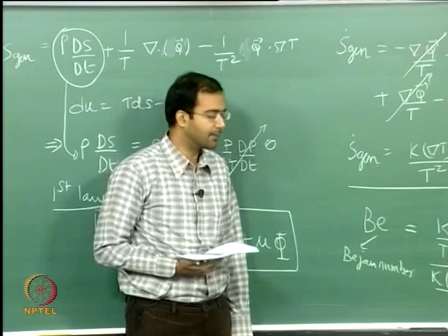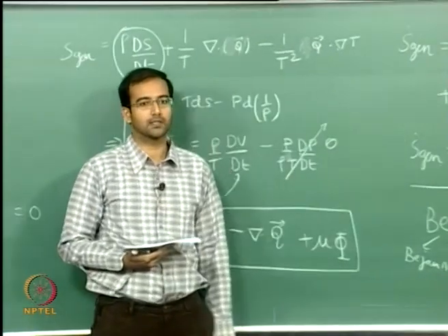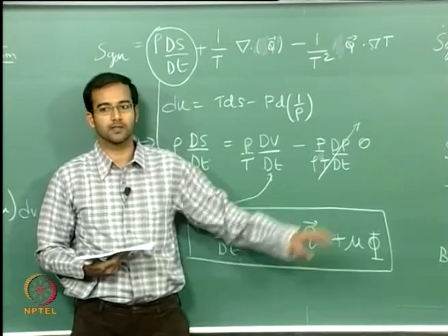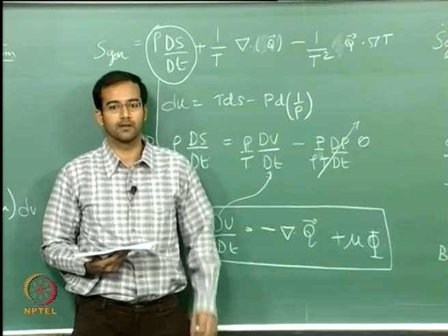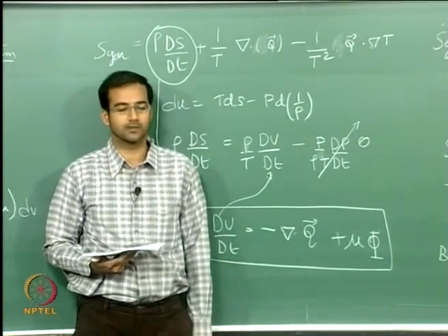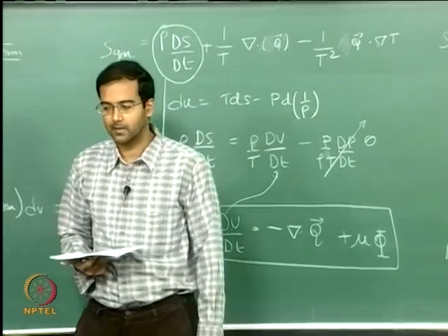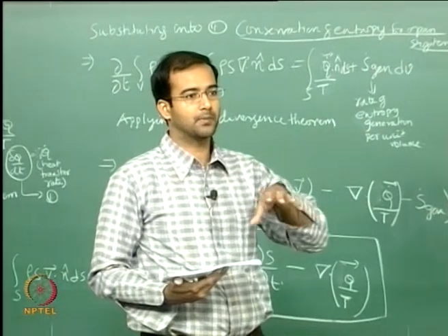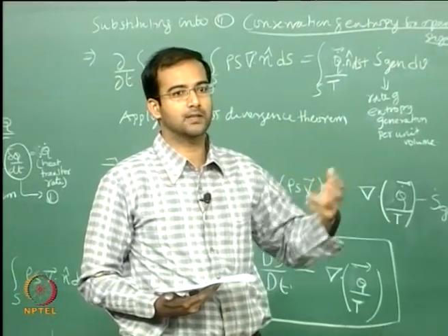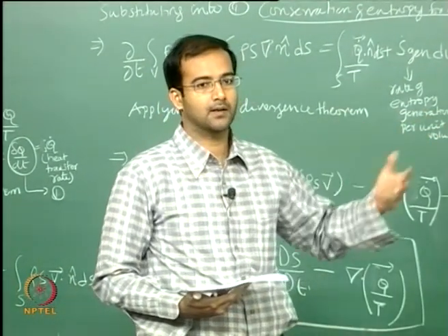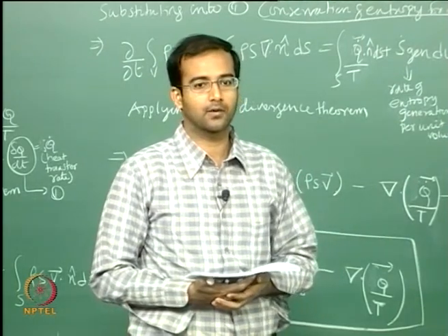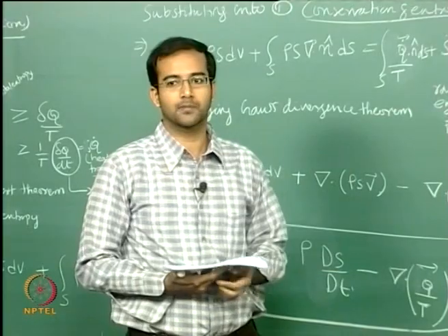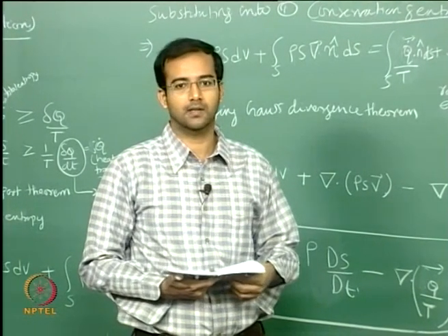So basically this can be plotted just like you plot your isotherms and heat flux lines. You can plot the entropy generation due to each of these and visualize how it looks. It's a very useful tool, and you can see in which location in a particular system your entropy generation is by the conduction part and where it is by viscous dissipation, and you can probably try to reduce the viscous dissipation by some method, so that will also reduce the entropy generation.